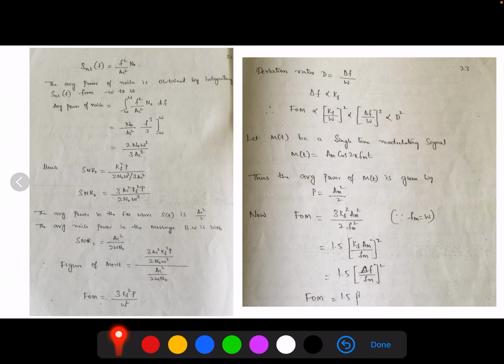So assuming that no signal is present and the carrier wave is unmodulated, the frequency discriminator output is given by x of t is equal to AC plus Ni of t into cos 2 pi fct minus Nq of t into sin 2 pi fct. So we have the equations. Individual clicks are heard in the receiver output. It is the indication that the receiver begins to break.